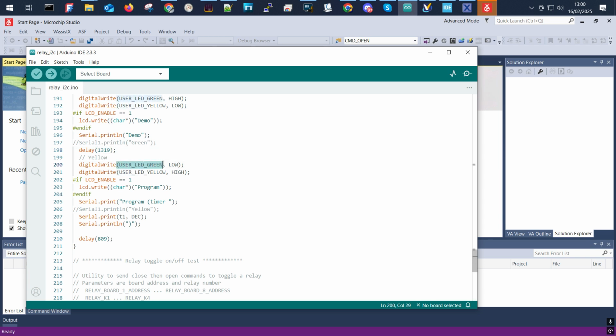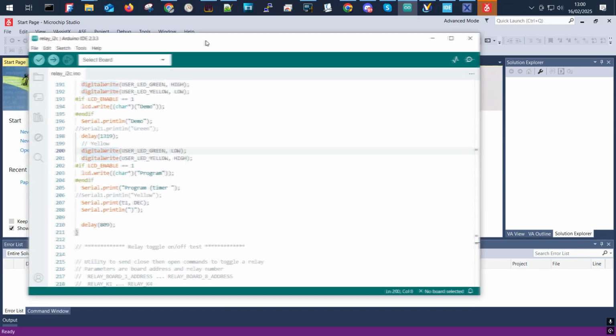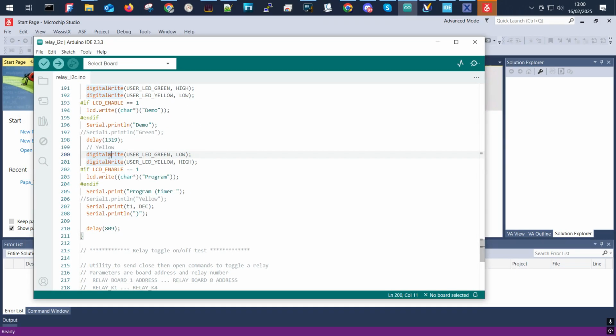And this uses a little bit of memory in the microcontroller, and also for every read-write operation it goes through additional code. It goes through an indirection inside of the microcontroller to map the pin we want to the controller physical pin. That's the vast variety of boards that the IDE supports, but there is a lack of performance inside of this, in the way the I/O are handled.